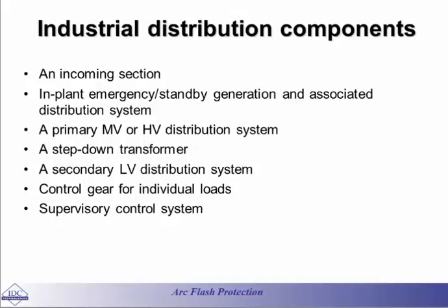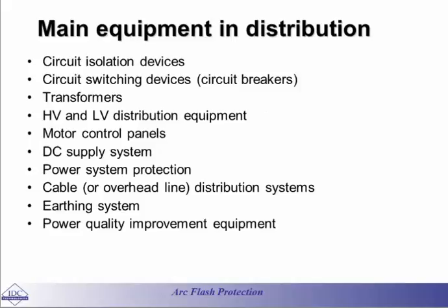And on some occasions, basically, you may need to have, let's say, something like embedded generation or standby generation or in-plant, in-house generation, emergency power or something that will be connected to the same bus bar at the LV side and sometimes at the HV side. So this is in very general the distribution system that you can think of.